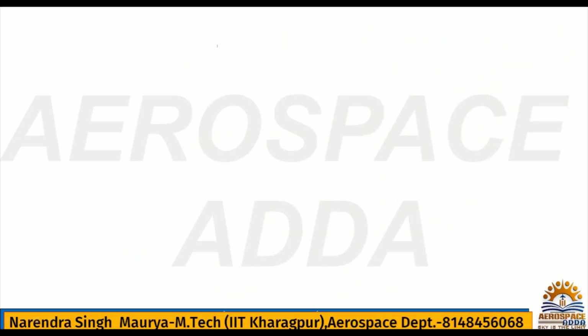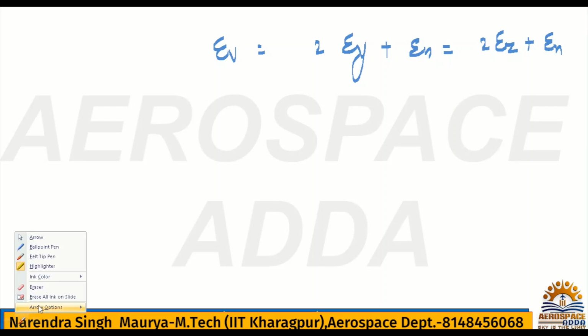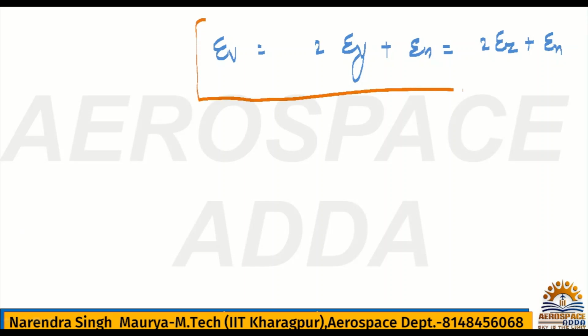In a few books, you may get volumetric strain equal to 2 times epsilon y plus epsilon x, or 2 times epsilon z plus epsilon x. So x means it is in the L direction, and y and z, I told you, are the same. So this formula is the volumetric strain for the longitudinal, for the circular bar.